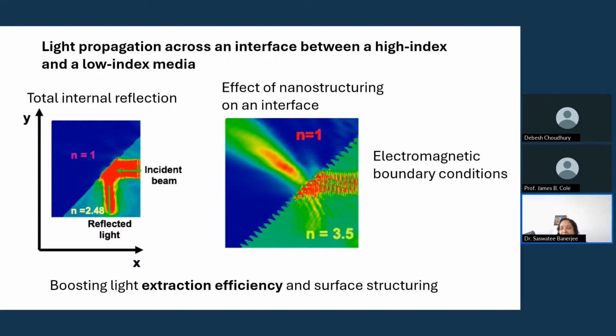It's kind of hidden. You are not really seeing the electromagnetic boundary conditions, and this is a good point about FDTD, because once you set the initial condition, it is automatically implemented. So you are not really seeing this, but you need to know that there are these electromagnetic boundary conditions, because if you are trying to solve this problem in the frequency domain, then you really need to consider them. So then just consider the right-hand side picture.